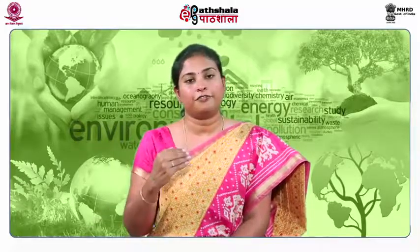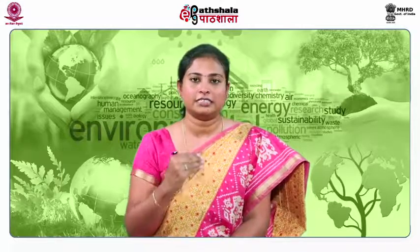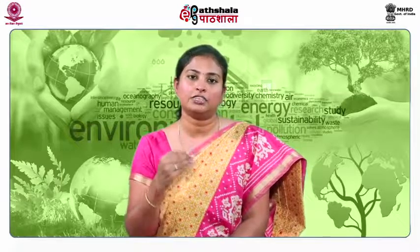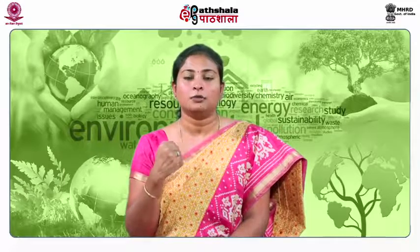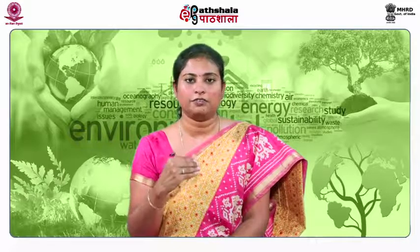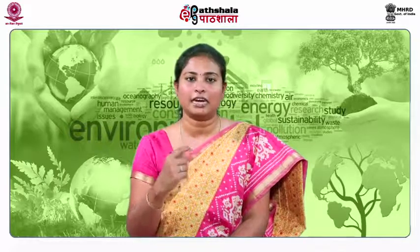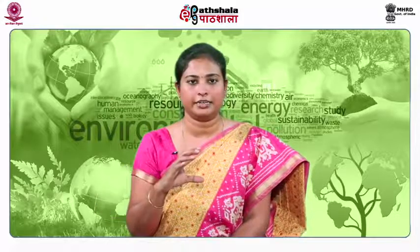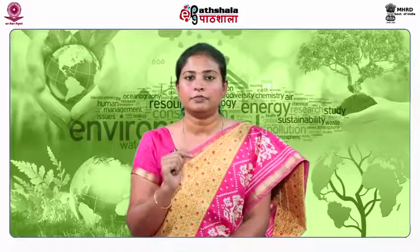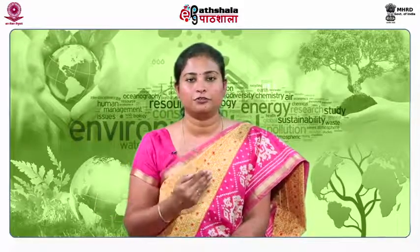Then you have to continuously monitor the waste density and settlement. The rate of degradation and waste saturation is determined from waste density monitoring. Monitoring of settlement on the surface of the landfill bioreactor might help in calculating the available space in each cell of the landfill bioreactor. This will also facilitate more loading of waste.